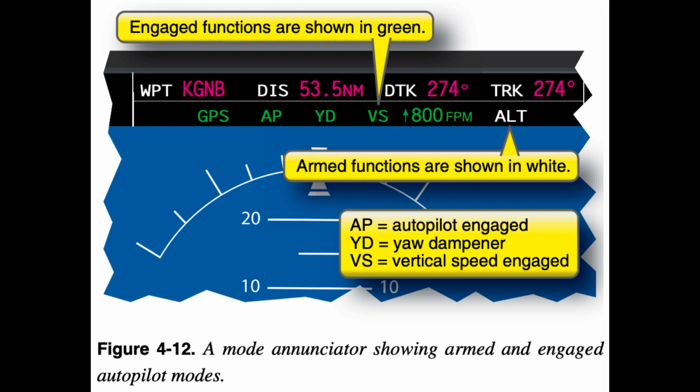the capture mode. This situation typically results in the aircraft climbing or descending beyond the assigned altitude, which may result in an altitude deviation. Altitude deviations are among the most common mishaps reported by pilots to NASA's Aviation Safety and Reporting System, ASRS. In any event, always monitor the actions of the FD/autopilot system and be prepared to fly the aircraft manually.